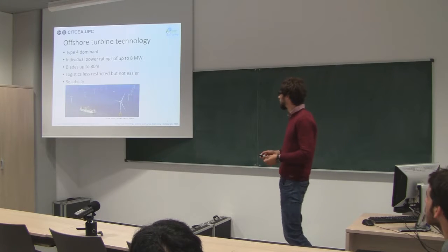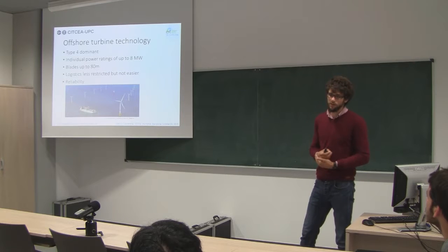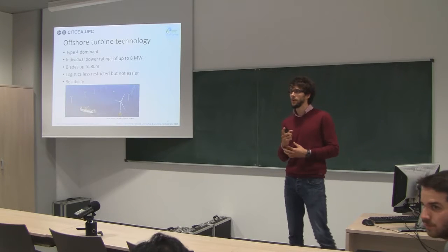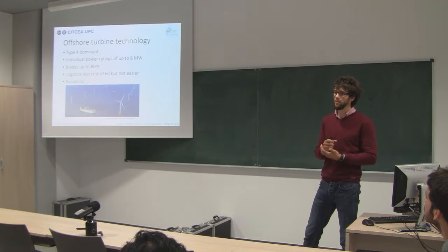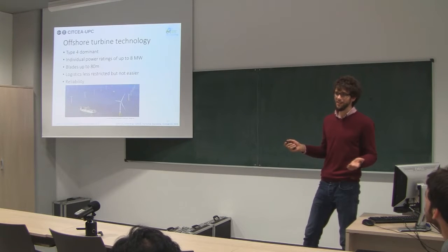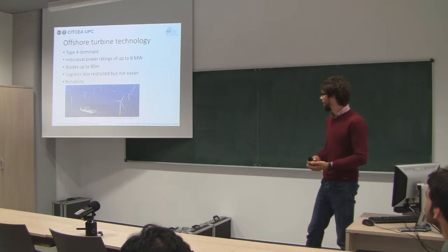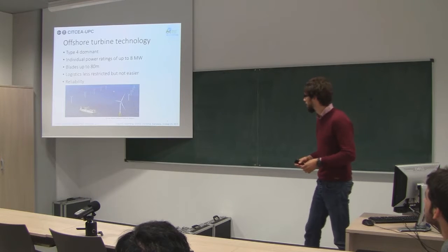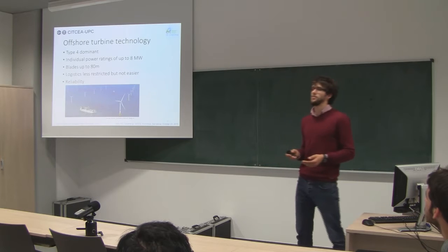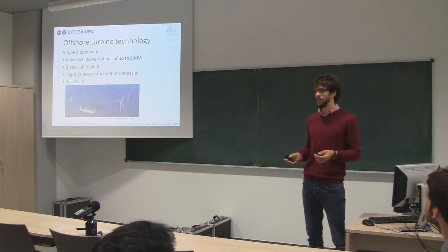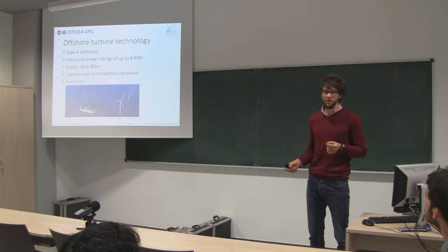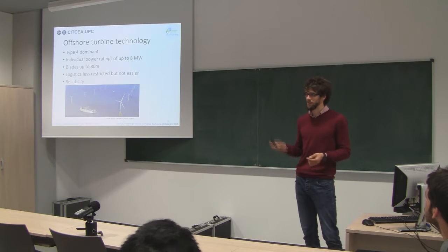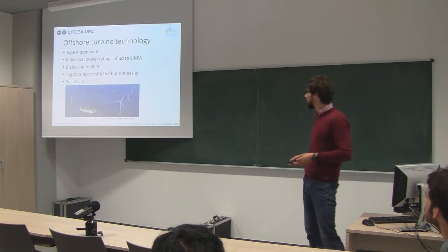Just to give you some figures, offshore the power rating of the turbines is increasing a lot, and that's maybe also a question. I think in the last row on the right you asked if there's still development in the turbines. Of course there's development. I mean, I think the car industry is also developing all the time. But as Edo said, 3 blades is nowadays state of the art. You don't try to have a higher tower, but if you want to extract more energy, you have to increase the size of the blades, because you want to sweep a large area. And then, of course, at some point you have to increase the tower size, because otherwise your blades are scratching the ground, and that's not very good.